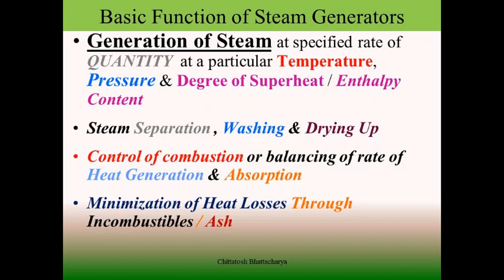Besides that, we need a proper arrangement of steam separation, washing, and drying while steam is generated. We need proper control of combustion, balancing the rate of heat generation and absorption, to safeguard the equipment so that the heat transferred across the heat traps is not damaging the equipment.